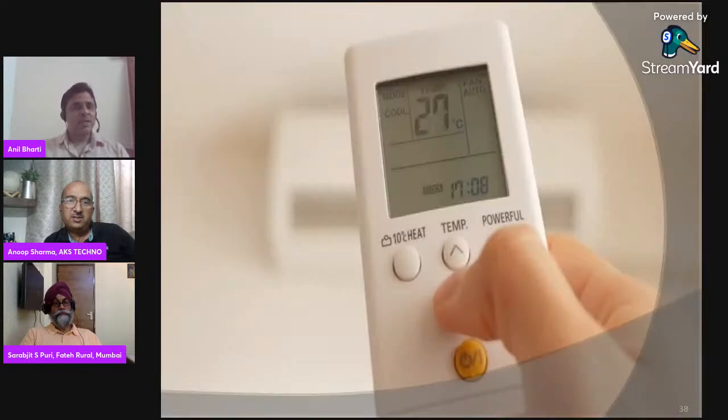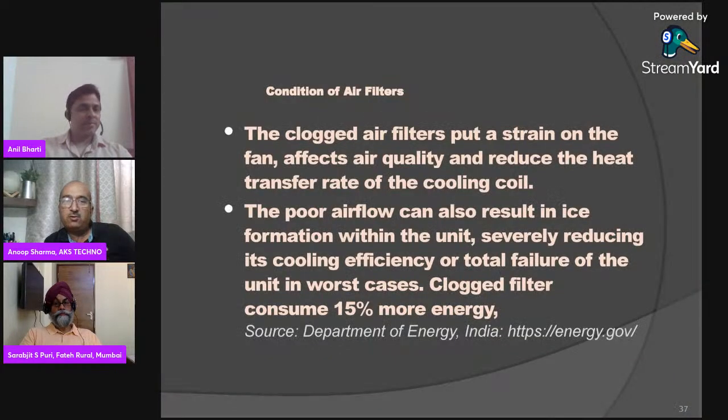So a few of the newer manufacturers have also given a provision to provide the pressure differential across the filter. So once your filter is blocked, an indication LED light is also given in a few of the ACs. If the pressure difference is very high, then there will be an indication that the filter is blocked.